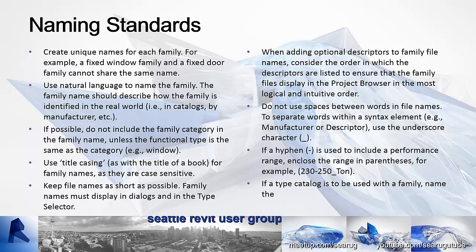And what you're looking at here is best practices. I'll show you where this document is and give you kind of an outline of it, but these are just some of the key points I like to point out inside of the naming. We try not to use spaces. We try not to use industry-specific terms. We want to keep it somewhat generic in the description. So it would be, in case of a window, casement, wood, manufacturer name, then a short little descriptor to it.